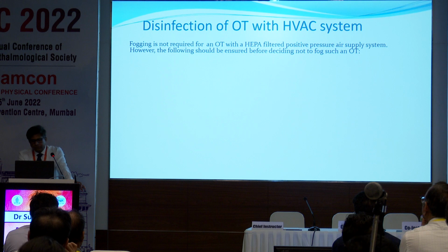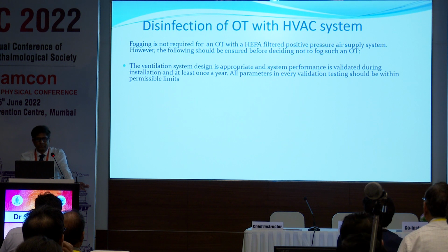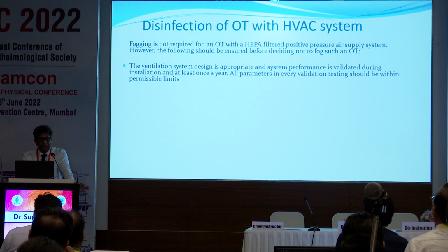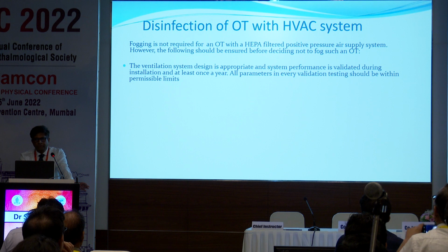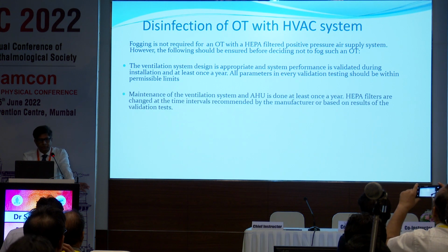So fogging is not required when you have an OT with HVAC system, but in this situation, you have to ensure that the ventilation system design is appropriate and the system performance is validated during the installation and at least once a year. All parameters in every validation testing should be within the permissible limit. You have to ensure that.